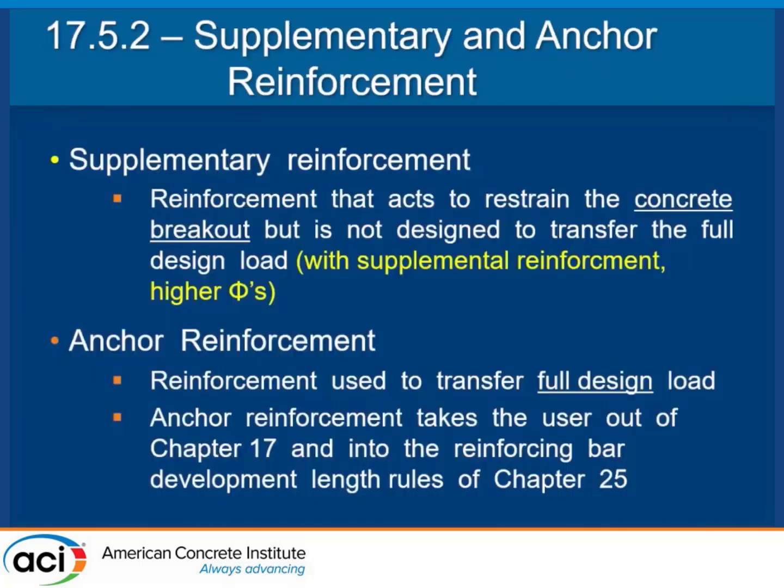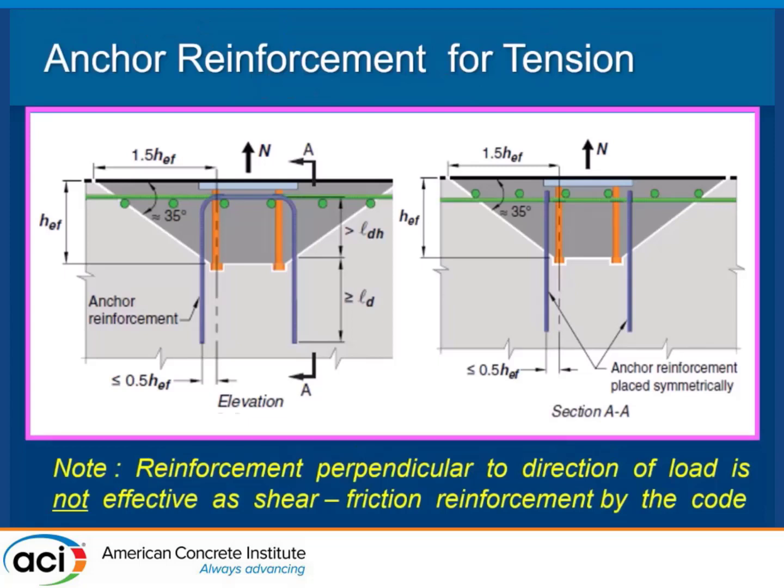Now we get to the supplementary reinforcement and anchor reinforcement. So yes, the presence of reinforcement around these anchors will increase the capacity of the anchor design. Of course it does, but how it does it is what's important. So we have two concepts in the code, one called supplementary reinforcement and one called anchor reinforcement. Let's look at a simple case for tension. We've got a plate, and let's say welded studs here, and you can see the tension concrete breakout, and let's say we throw some, in this case we'll call it anchor reinforcement, in there.